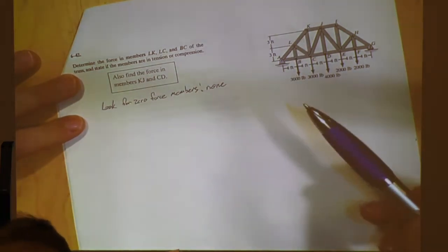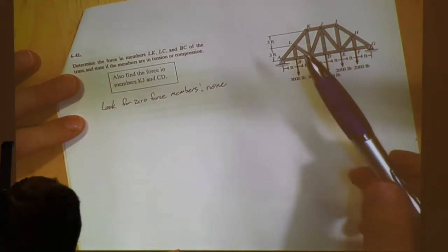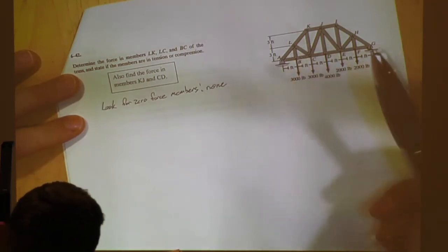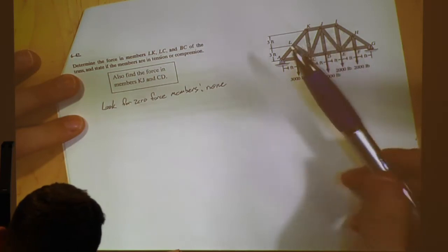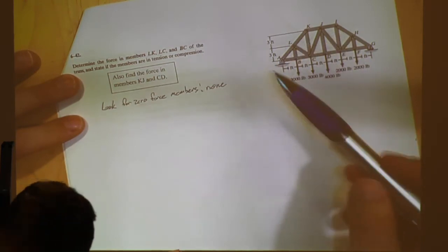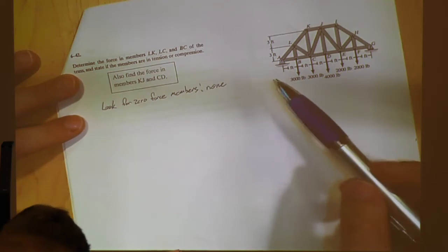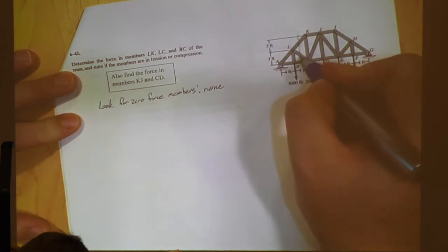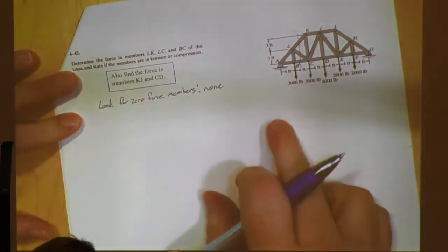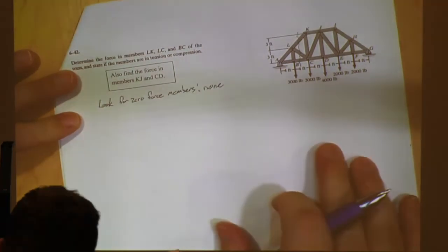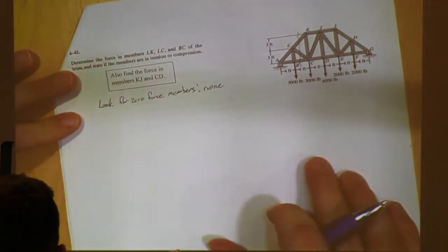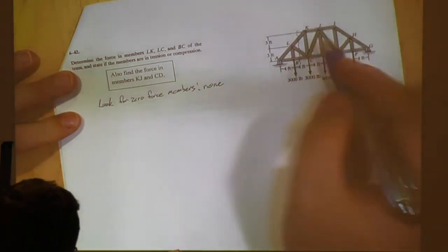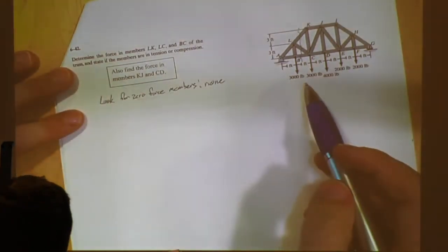So we know of two methods, right? What are the two methods for solving a truss? So sections and joints. Can you solve this with joints? Yeah, you can. Do you want to do all that work? No, you don't. So if you notice that they're all through one area, you can say, all I need to do is cut it. But once you recognize that cut, which side are you going to start on? Does it matter? Can you use this side or this side? You can use both sides, but one has a lot less work. Why?